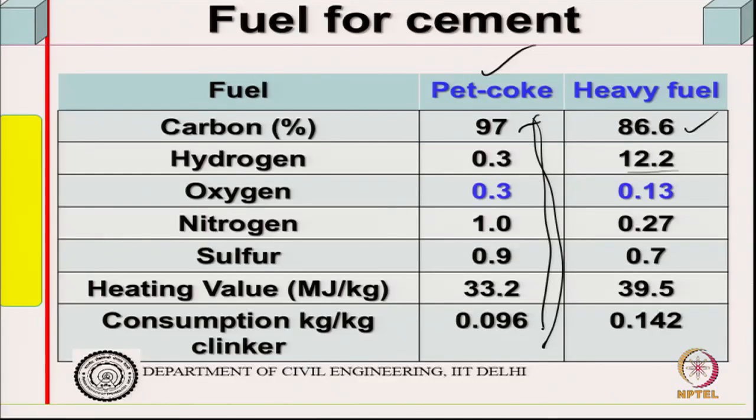This obviously comes from the petroleum refineries. Now, generally they will have carbon, hydrogen, oxygen, nitrogen, sulfur. So, when you heat them up, obviously the carbon goes to carbon dioxide, hydrogen to water, no problem, and the oxygen, some part is there, very small, but at high temperature they produce NOx, from atmospheric oxygen as well, and sulfur dioxide. So, that is how they come. There may be other compositions of fuel of varieties of kind, but when we talk about alternate fuel we will see what the advantage is.